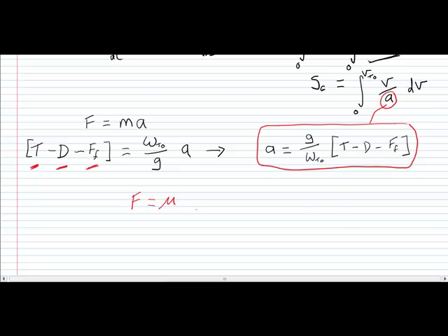And we define this thing called mu, the coefficient of friction. But the reaction force of our aircraft will not simply be the aircraft weight, because as the aircraft accelerates, it will be starting to generate lift. So the reaction force provided by the ground will be the takeoff weight minus any lift that the wings are producing during the ground roll.